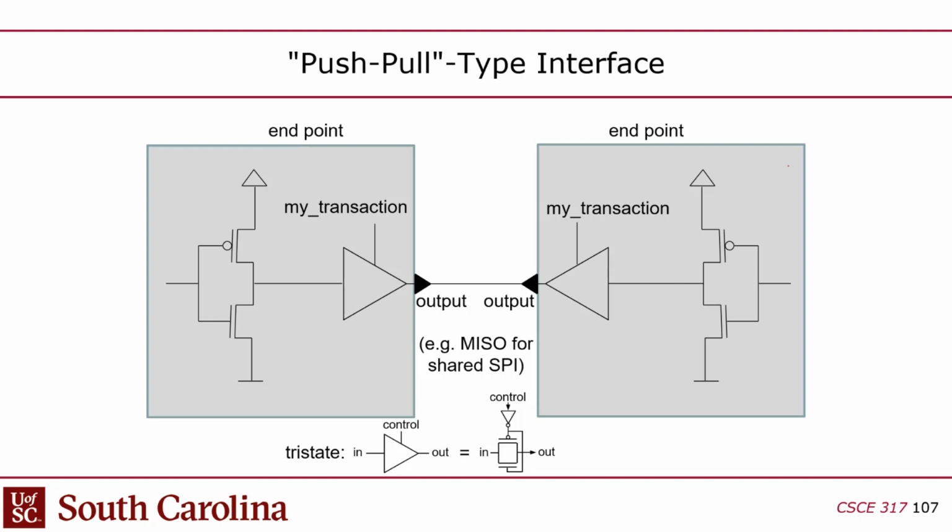When you turn this guy on, you want both transistors on. See, in this case, only one transistor is on. But in a transmission gate, like a tri-state buffer, you want them both on or both off, so you have to add an inverter. So now you've got 2 transistors here, and another 4 transistors in the tri-state, and they're big. They're all big transistors too, because they're driving an off-chip load. So this is 6 transistors. It's pretty big. It's expensive.